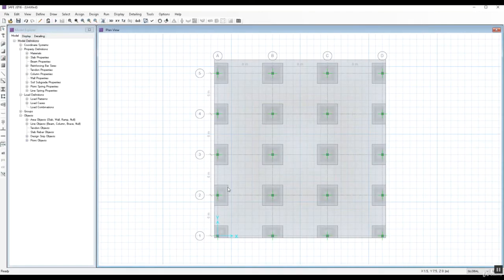this is 3 span by 4 span. From each side I have half meter, here 0.3 meter. I leave this small, and here 2 meter. This is the column size and the material, everything is ready. You can make run now. But this is not usually what we work with, because we don't have replicated columns like this in a normal building. For that, I made one template to see how to make it.